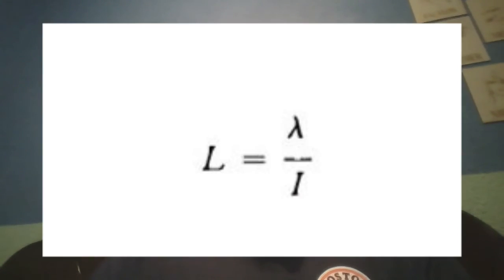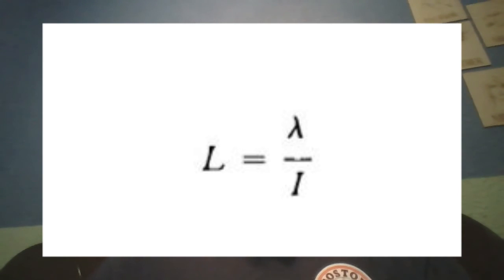Inductance of a conductor due to internal flux. The inductance of a transmission line is calculated as flux linkage per ampere if permeability μ is constant. Sinusoidal current produces sinusoidally varying flux in phase with the current. The resulting flux linkage can then be expressed as the phasor λ in the next formula.